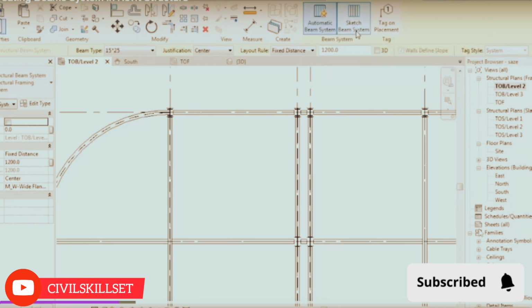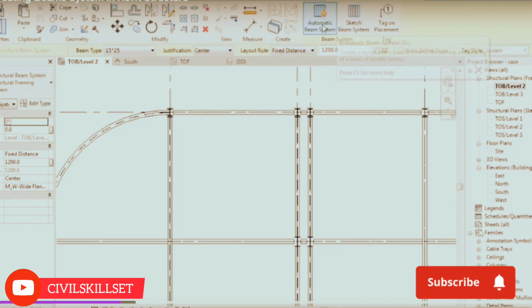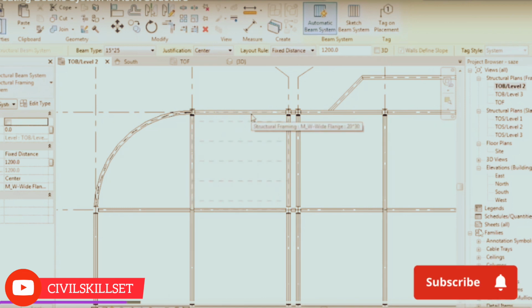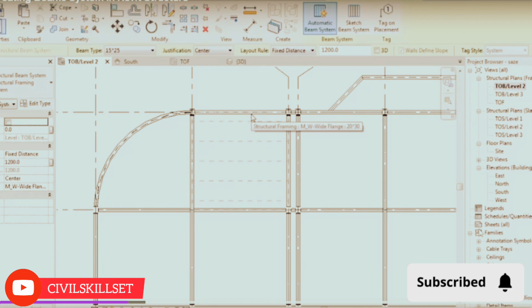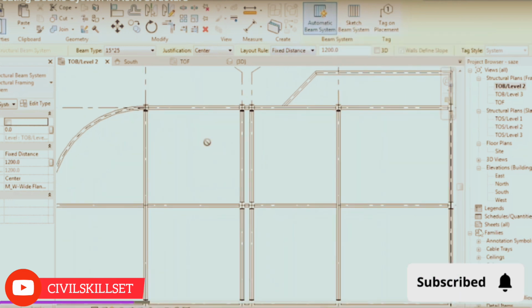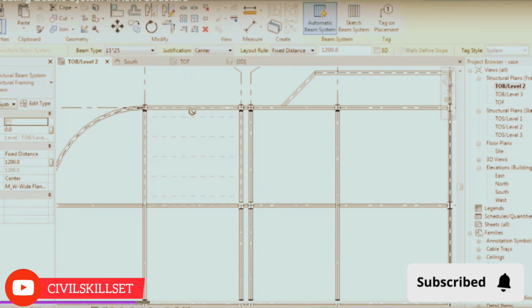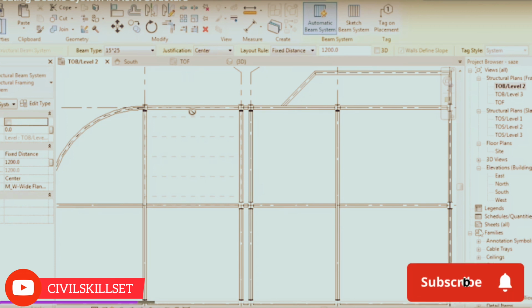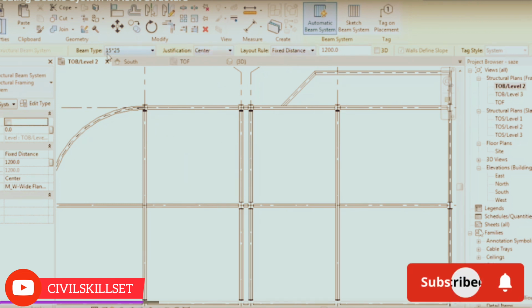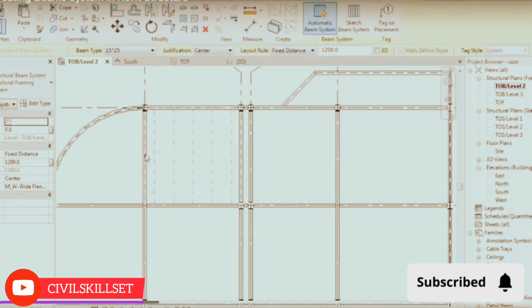This system works in two ways: automatic beam system, sketch beam system. Automatic is for these parts. In each beam you stand, you will have more beams parallel to the first beam you're standing on. And we usually use this. I will tell you what a sketch does later. So I use automatic beam system. I use the beam type, justification, layout rule, and all that. You see?